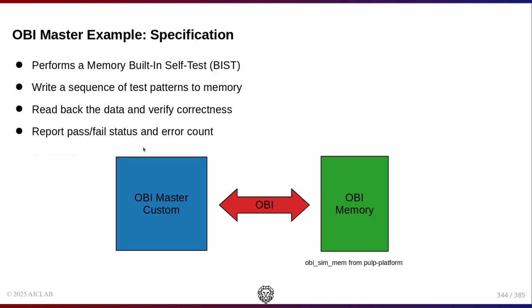OBI master example. We plan to design an OBI master module for memory built-in self-test, or BIST. The module must write data to the OBI memory, read data from memory, and compare it. It must also report a pass or fail status and total error count. We will use the OBI sim mem from PULP Platform to validate our design.